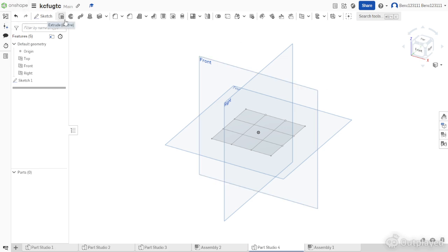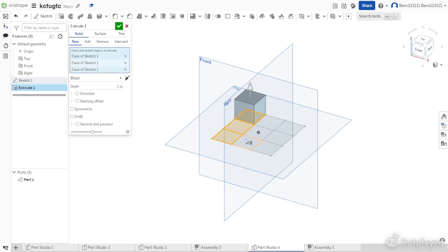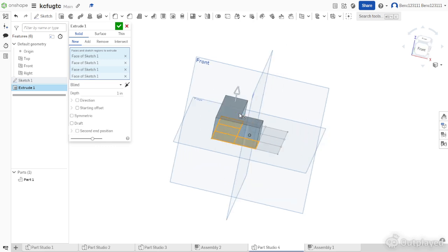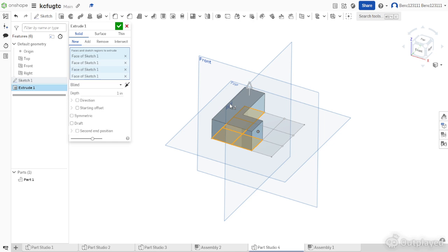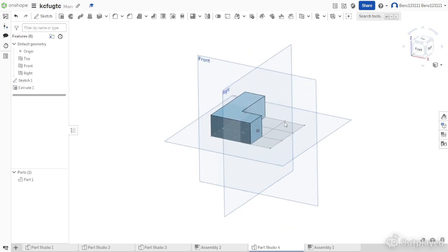So then from here, you will have your own cube that you will have created in 7th hour. You want to take this extrude, and go for each first part. So your first part was an L, or rather an L with a block up here. If you have an extra block instead of just an L, you have a bit more stuff you have to do for this. However, we're going to start with just the L. Make sure the sketch is still visible. We will go into hidden. Once you finish your first extrude, you want to make it to where it's not hidden. It's shown. So you can see we have the 3 by 3 cube at the bottom of it still.